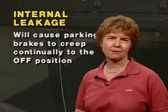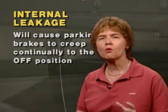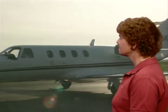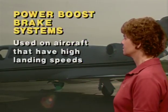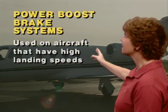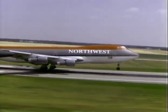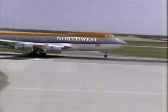Now, as aircraft get faster, they need more than just the master cylinder to help them in getting stopped. So power boost brake systems are used on aircraft that have high landing speeds. A 747 needs a lot of power in order to stop it. So power brake systems are designed for aircraft that need a large volume of fluid to operate the brakes. And in power brake systems, you're going to be using power brake control valves.